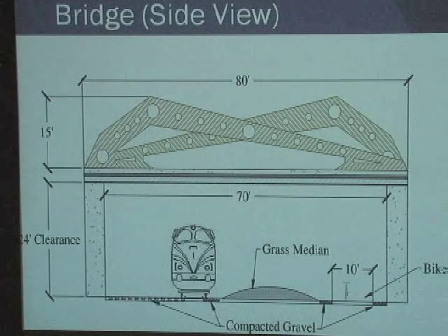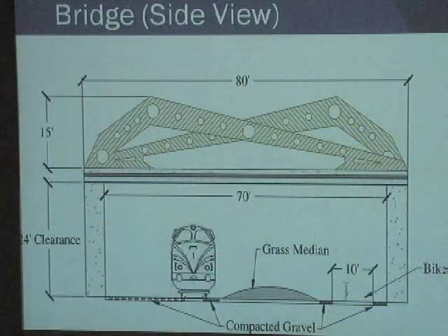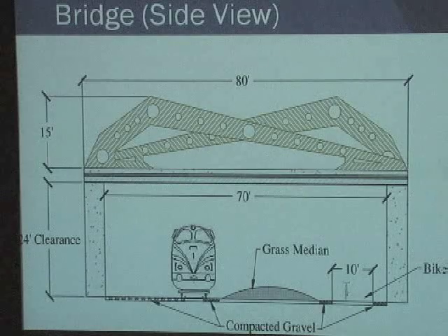This will be a single-span bridge with a design strength for an HS20 live load. To do that, we'll use 6 W24 by 104 steel beams to support the cast-in-place reinforced concrete deck. It'll be 7.5 inches thick. The road will have 12-foot lanes and 5-foot wide sidewalks for pedestrians.